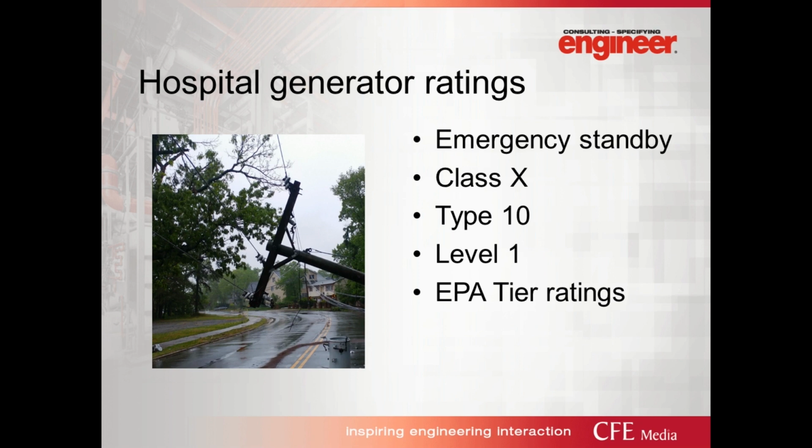NFPA 110 also recognizes just 2 levels for equipment performance. Level 1 systems are where failure of the equipment to perform could result in the loss of human life or serious injury. And level 2 is basically everything else, so where failure or performance is less critical to human life and safety. So as you can imagine, a hospital is a level 1 system.